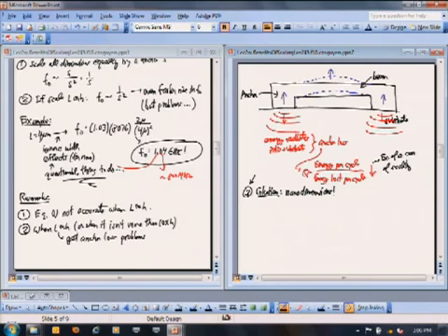But nothing is perfect, right? When you make it too small, and so this means, make this clear. This means H is going to be about 300 nanometers. L is going to be about 1 micron. Okay? That's a pretty small device. Okay? And one of the problems that you run into when you make a device that small is that the power handling of the device goes down.